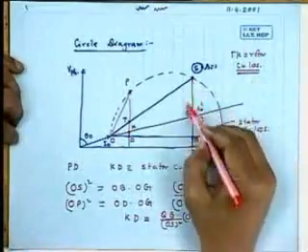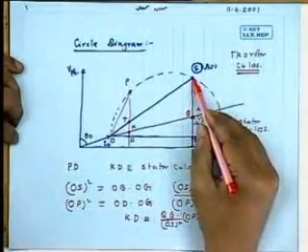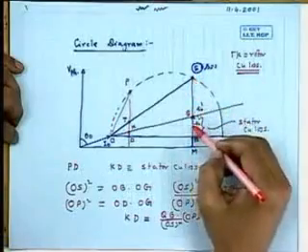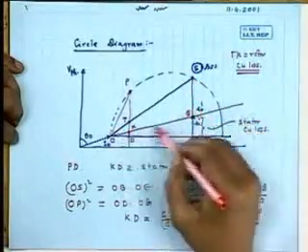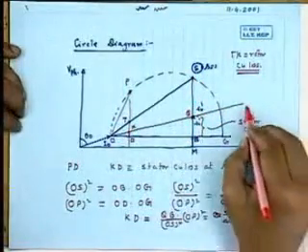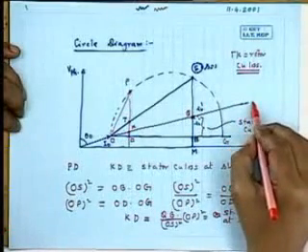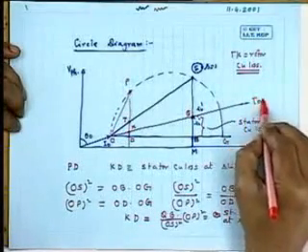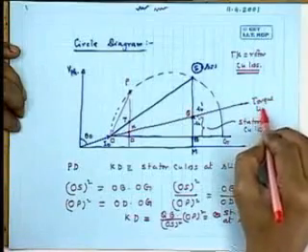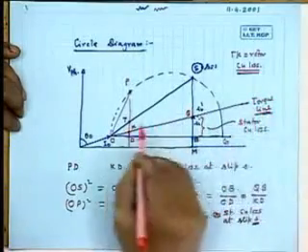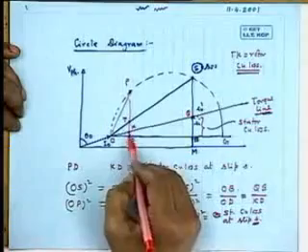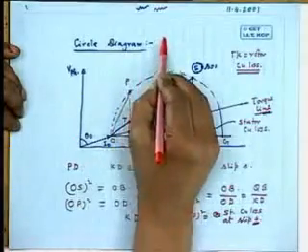So, by dividing this standstill length, that is SB, in the ratio R1 is to R2 dash, you get this one. And as I told you, this length is called the torque line, because the length PK is the air gap power.